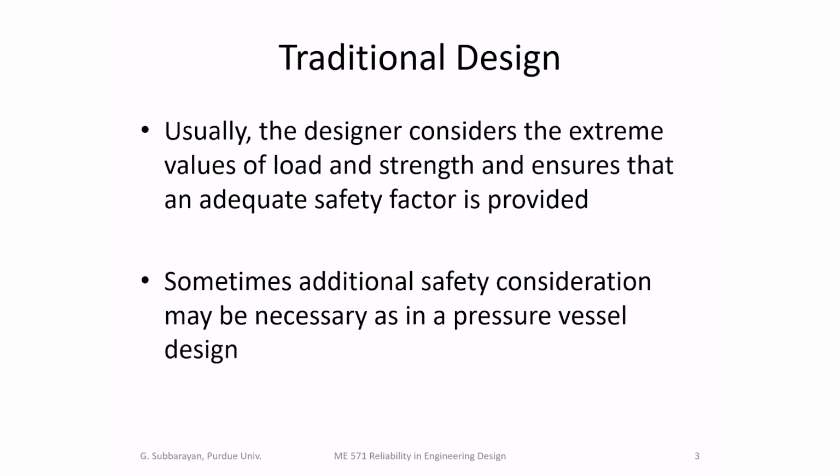So we basically use a safety factor to ensure that the load, the stress, for instance, will not exceed some allowable stress, which is strength, nominal strength. Okay, nominal, because it may not be the real. It's nominal strength divided by some safety factor. So the allowable stress is nominal strength divided by a safety factor, and we ensure that the stress is always lower than the allowable stress.